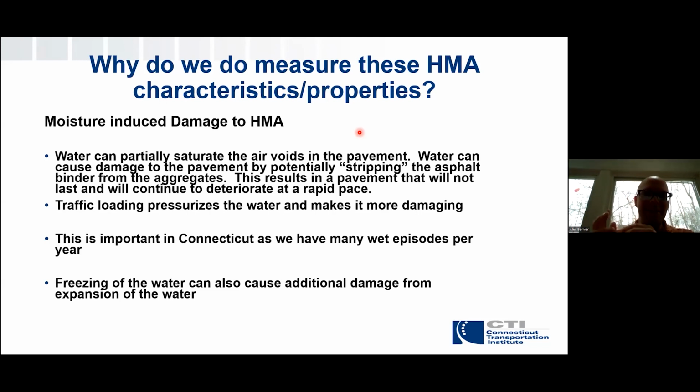And what happens here is there's all sorts of intermolecular forces. That's the word I'm looking for. Friday mornings, right? It's tough. We've got a lot of molecular forces acting on the asphalt and the aggregate and water. So you'll probably recall from science class that water has some sort of polarity associated with it, right? It's different than a normal molecule because there's some sort of magnetism in there. Not necessarily magnetism, but subatomic, you know, electrical charges. And the same thing happens in asphalt and actually in rocks in aggregate.